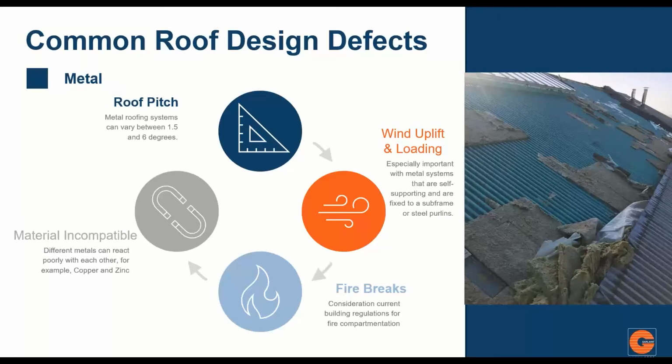Fire regulations and fire breaks, this has become a huge talking point over the last few years, and this has to be stressed at the design stage as well as on site. So we should always have a fire strategy in place, and we should also have a fire officer signing this off and checking for compliance. And as mentioned, we need to see this at site stage. We can't just rely on the design details, because often this is misinterpreted, and on site we end up with a defective design because it hasn't been followed as per the drawings.